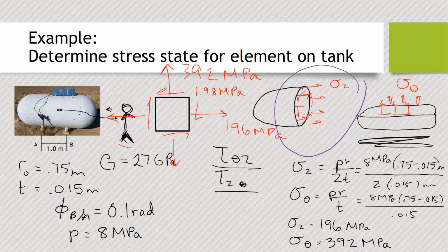One is that if you have this section cut, say that's point A and that's point B, we know that the torsion must be going in that direction because that's how you get the counterclockwise rotation of B relative to A. On this near side, that torsion creates a shear stress that goes in the same direction as the torsion. It's then resisted by the reaction, which would be on the back side.